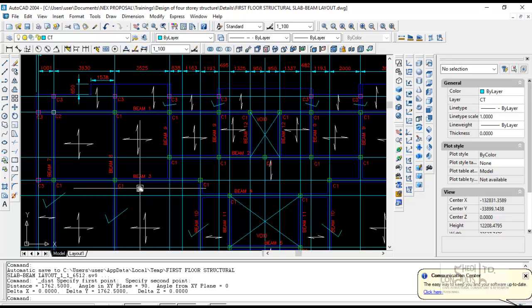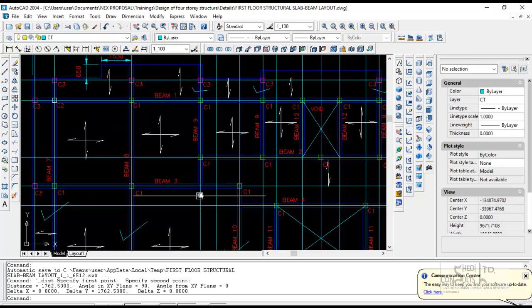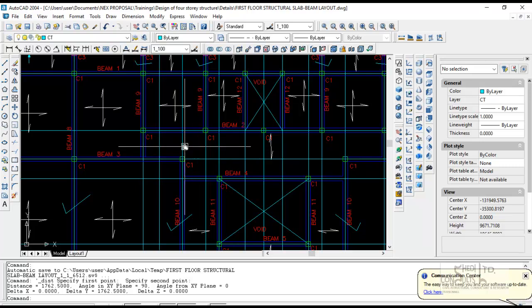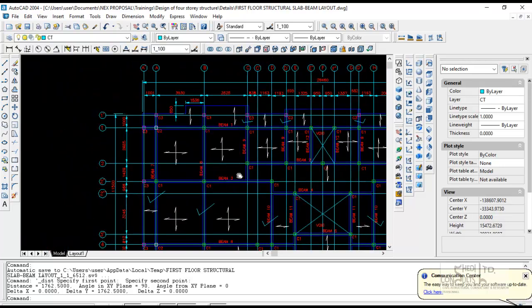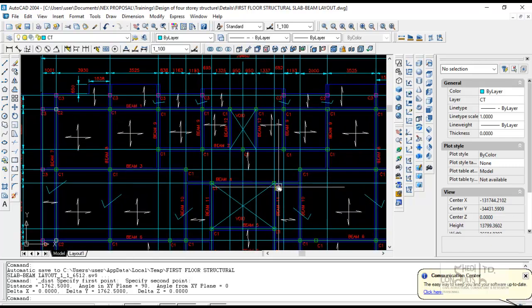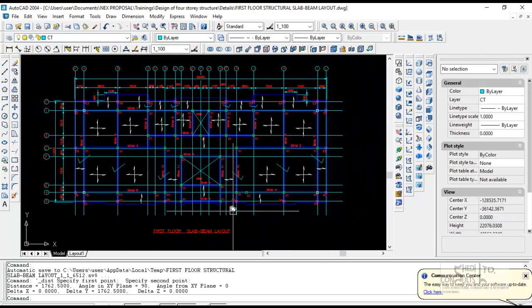So the beams are all prismatic, implying that they have a consistent cross-section throughout their entire length. We do not have tapered beams for the purpose of this analysis. They are isotropic, implying that the elastic properties, the elastic modulus of rigidity, and the Poisson's ratio at any point along the profile length is the same in all directions. That's the definition of material isotropy. So the beams are isotropic and homogeneous, in addition to the fact that these beams are all prismatic. So this is the first floor. We'll start by creating the member size on the first floor.